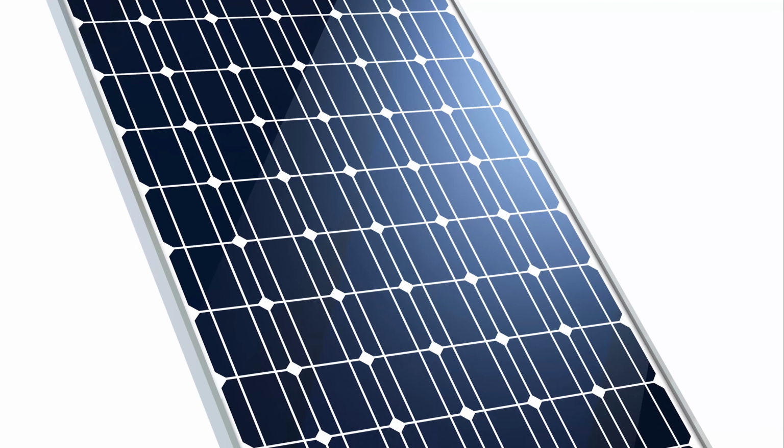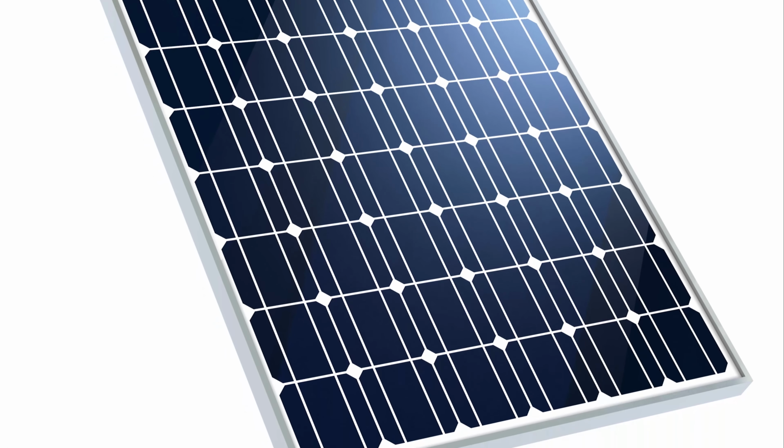Nowadays a typical solar module will be about 17% efficient. That doesn't sound too impressive, but when you consider that the sun is a free resource, it puts things into perspective. What the efficiency really tells us is how big a solar PV module needs to be to produce a certain amount of power. The standard test conditions I mentioned earlier use 1000 watts per square metre as the standard level of irradiance for testing solar modules. So if a solar module has an area of 1 square metre and can generate 170 watts of power at STC, then it would be 17% efficient.